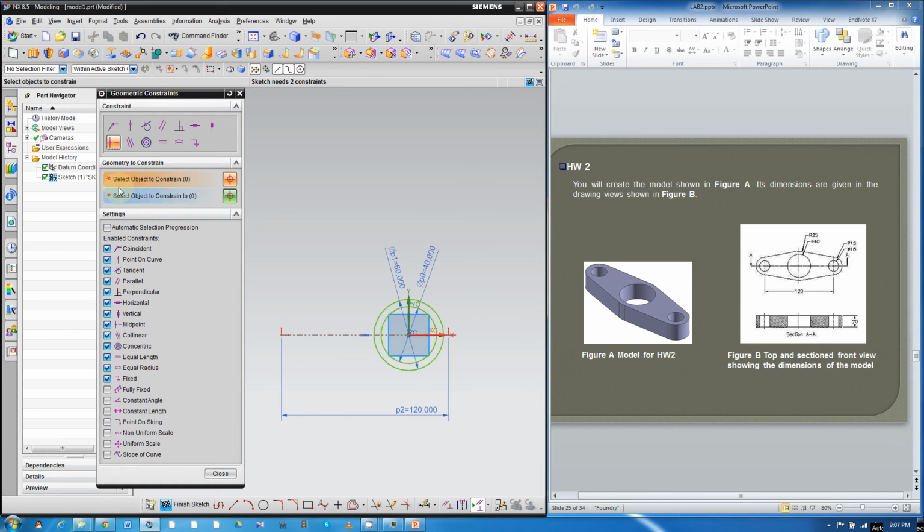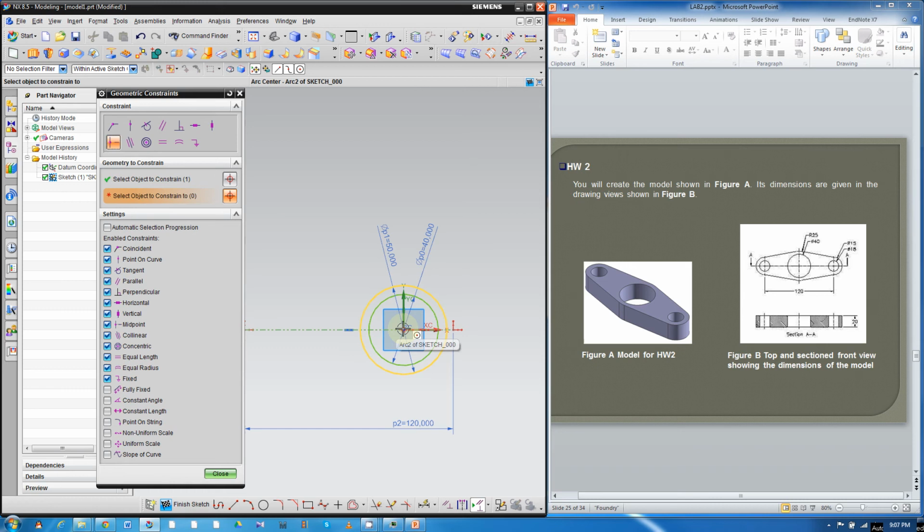So that's gonna be the reference line, and the reference line will be constrained to the sketch origin. If you hover here, you're gonna pick the center of the circles. So actually we want to pick the sketch origin. So we will hover here and wait for the 3 dots. Then we can click, and that's your quick pick menu. We can pick the overlapped sketch origin.